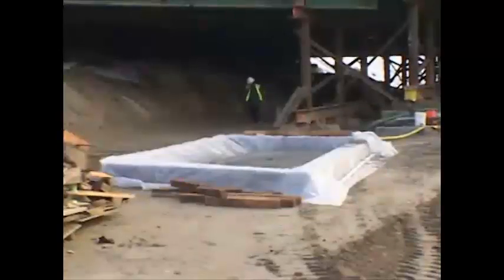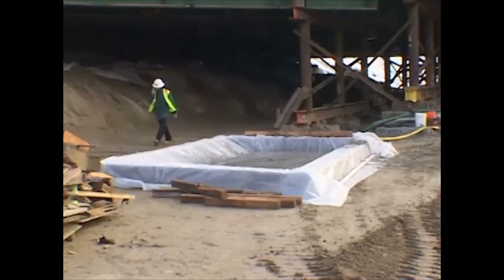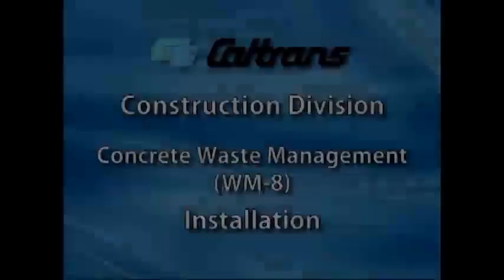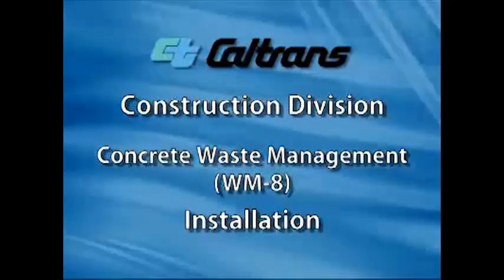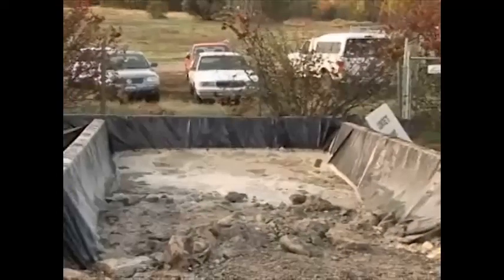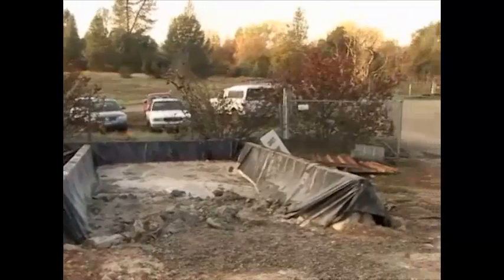Concrete washout facilities must be installed, maintained, and later removed at the locations shown on the approved stormwater pollution prevention plan and in conformance with details shown on Standard Plan T59. Temporary concrete washouts must be installed before the placement of any concrete at the project site.